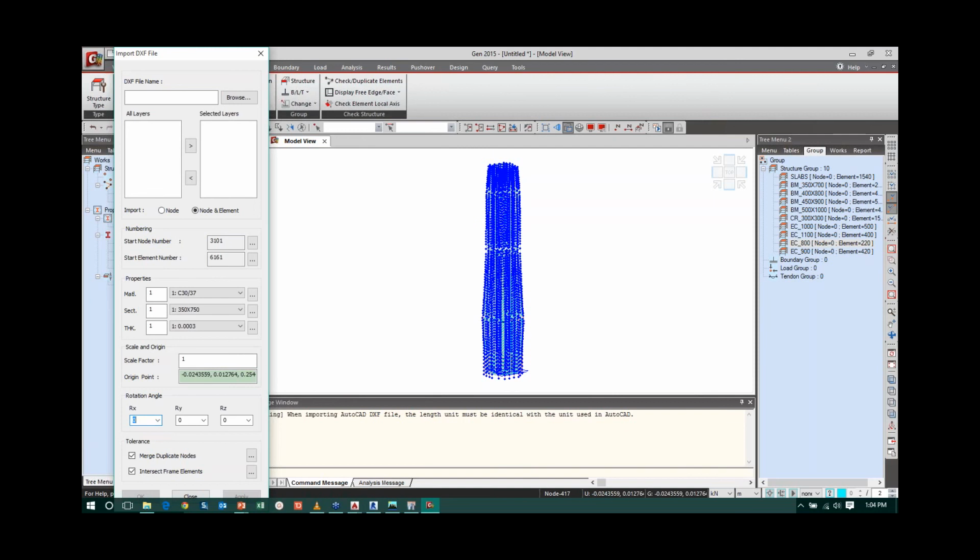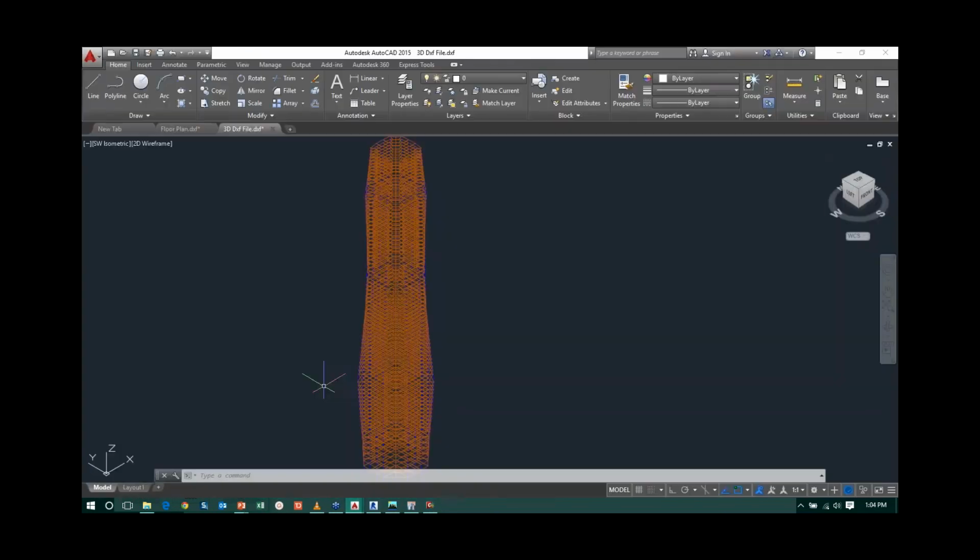And the next question is, how can we believe this is the critical axis? So critical axis, that way actually there is no right way to say, but you need to check both. You need to first check the AutoCAD drawing, in which plane your floors are lying in the AutoCAD drawing. So either it is in XY plane or XZ plane. So that gives you an idea along which axis we need to rotate. So for example, if it is in XY plane, so in MIDAS also the vertical plane is XY plane.